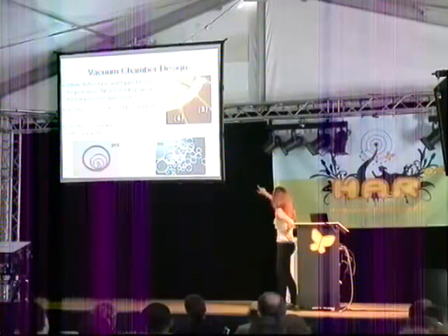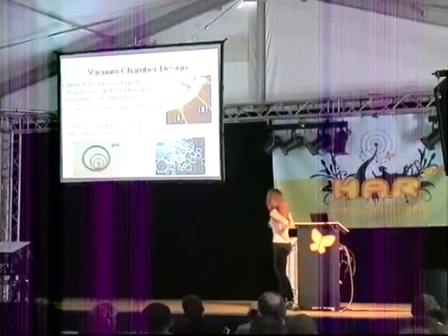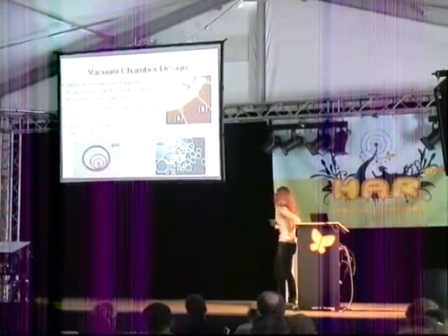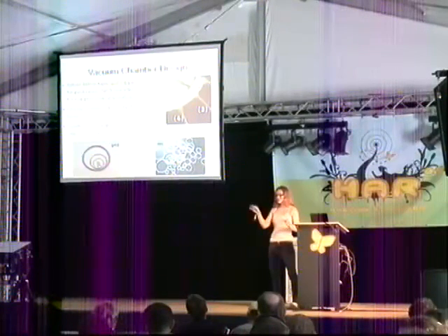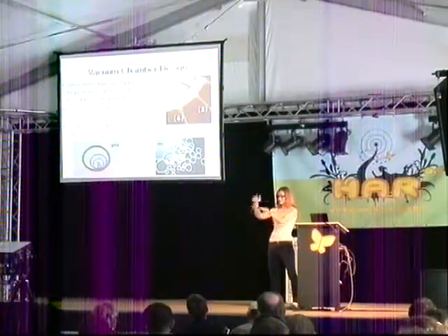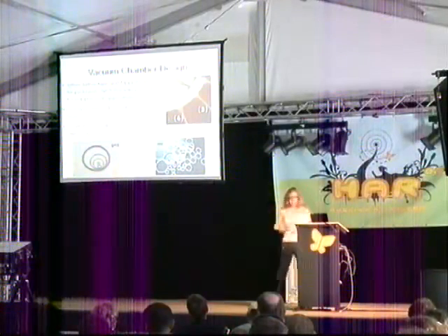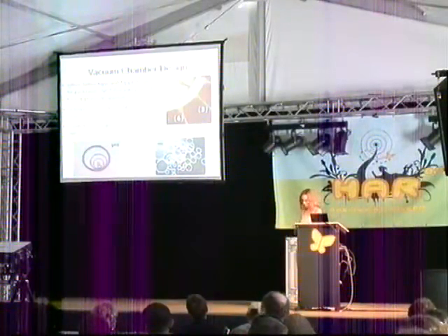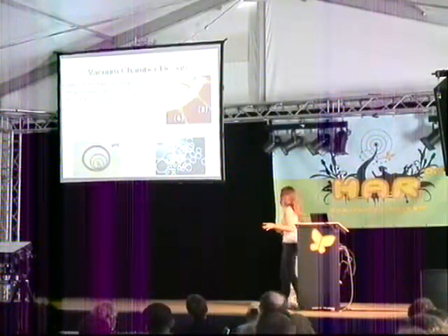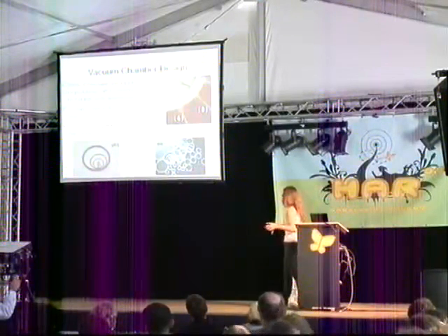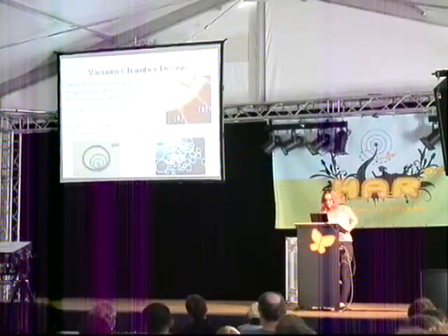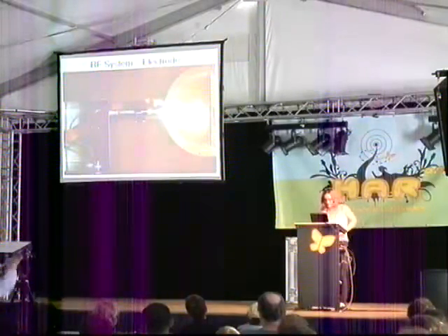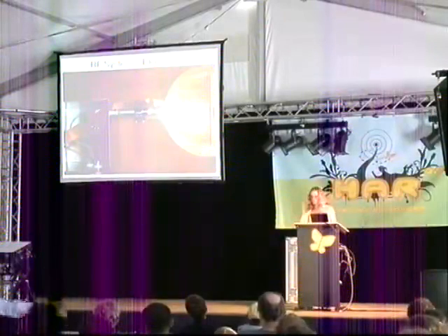There's also a very good website on gland design. I give that URL there. And that just shows things like, well, if I have an O-ring of this diameter with this cross-section, I want to make the width of the gland this much, the depth this much. So it's straightforward. Also, a brief aside on the type of O-rings you should use. Rubber O-rings, yes. Teflon O-rings, you don't want to use those. Those are for rotating applications. Okay, so that was the end of the vacuum chamber design section.